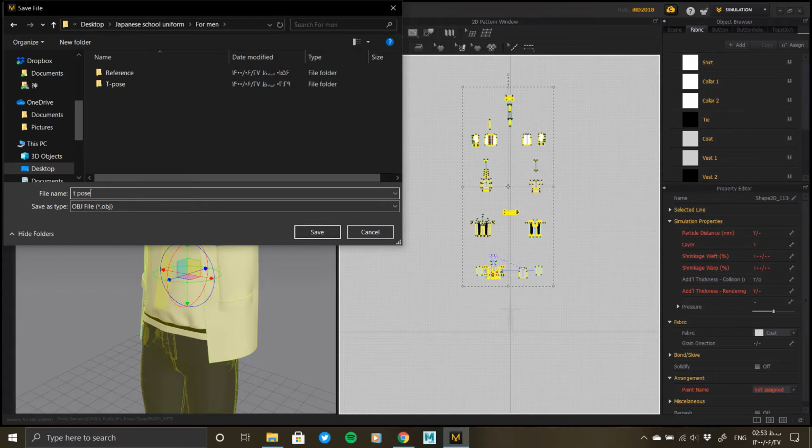Select the single object mode, and choose one of the three modes, thin weld, thin unweld, and thick, based on our needs. In thick mode, the UV of the thick parts is not defined. So in the case of thick output, it is better to define UV thickness separately,